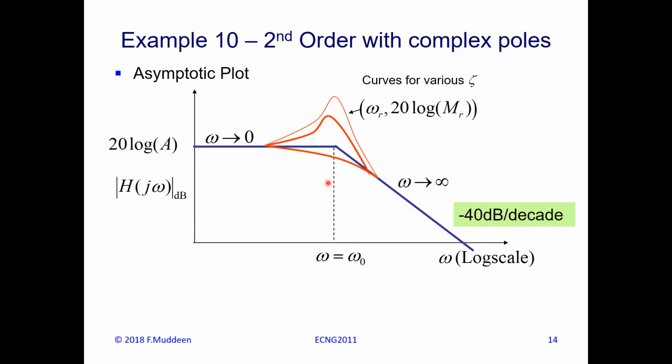So for lesser values of zeta, meaning as zeta tends towards 0, we're going to see a more prominent peak accordingly. But as zeta tends towards 0.707, we're going to get our natural curve, which is the actual Bode plot here. And this maps more towards the minus 3 decibel cutoff point that we observed in previous lectures.